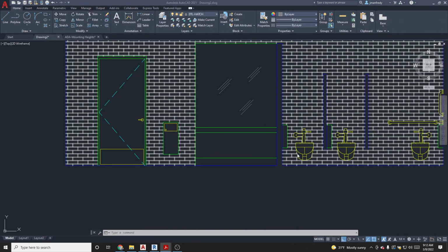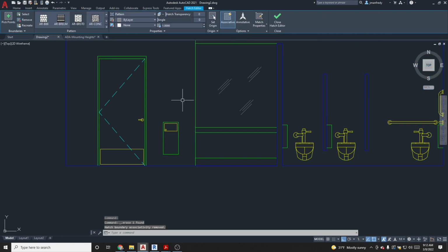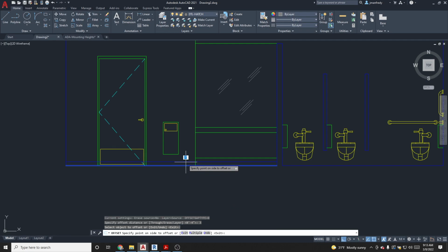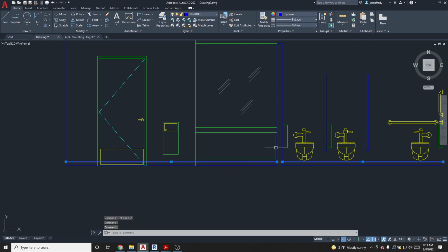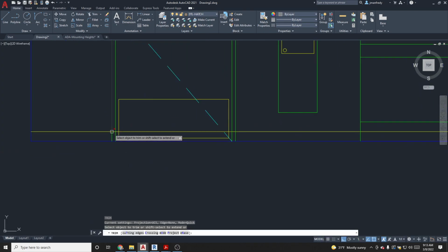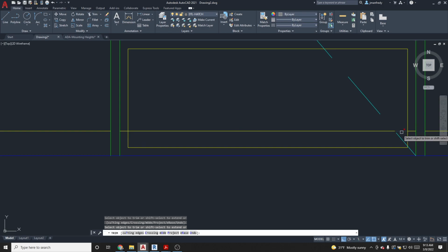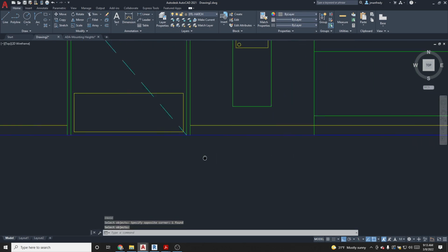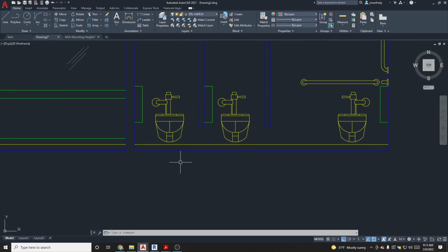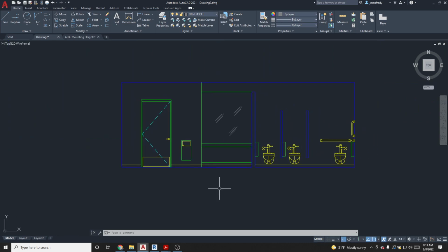So I left that out by mistake. So let's go ahead and delete this. Let's go ahead and offset, O for offset, 3 inches. And let's draw a little line across the bottom of the floor on detail fine layer. And let's make sure it appears. It can go through the door, obviously, so TR for trim. And make sure you cut it out of here. It goes across the bottom of the wall, here, here, underneath the sink. That's fine. Underneath these toilets here. Detail fine layer.